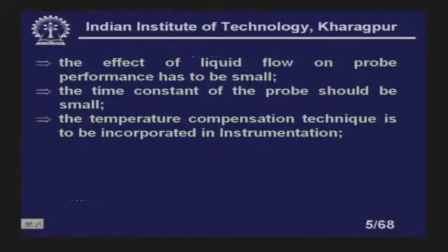Anyway, temperature compensation technique is to be incorporated in instrumentation, because if the temperature changes, many properties of the probe will change, since the electrolyte properties will change. So, some sort of temperature compensation, or more precisely the ambient temperature compensation, should be incorporated as part of the instrumentation.